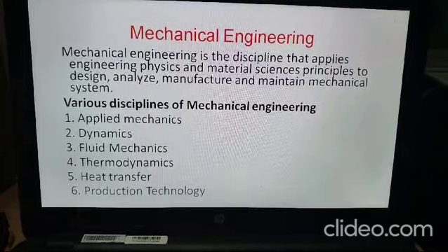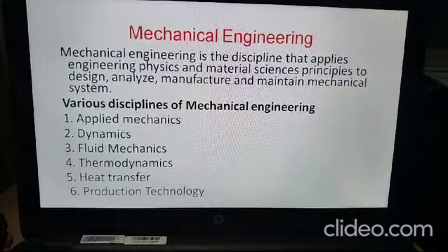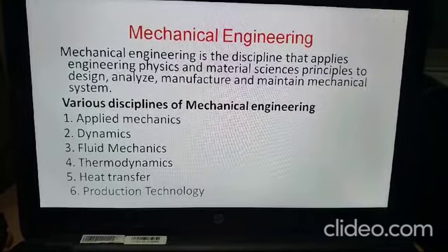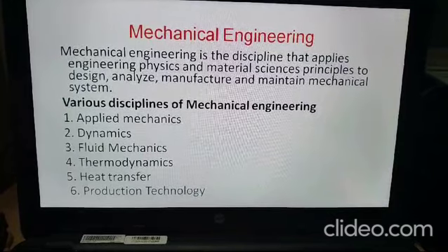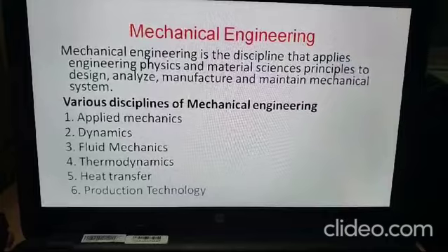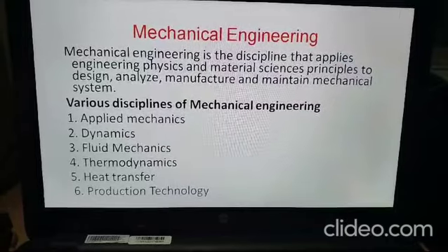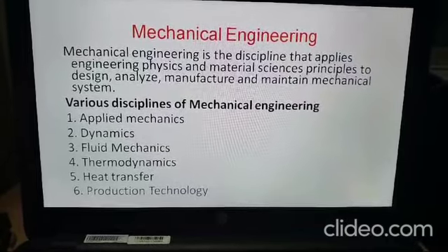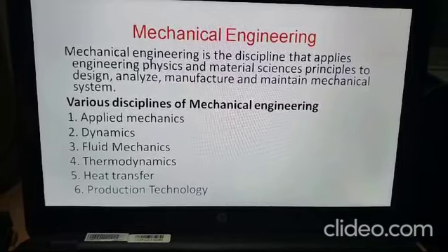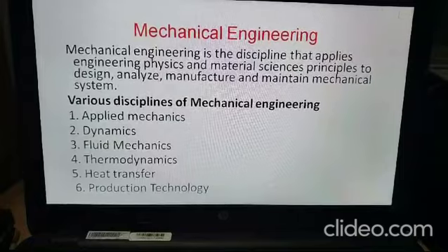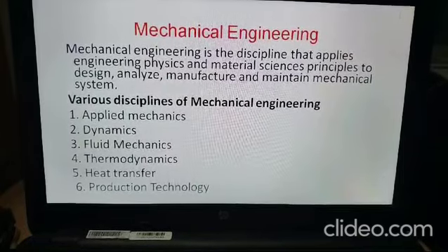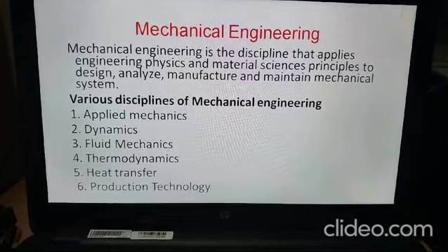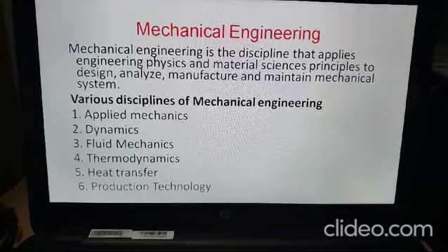That is called analysis. Then for manufacturing of products, we can use casting. Casting means we have to melt the metal into a molten stage. Then there will be a die cavity for the required size and shape. In that the molten metal will be poured, and after solidification the final product will arrive. That is called the casting process.